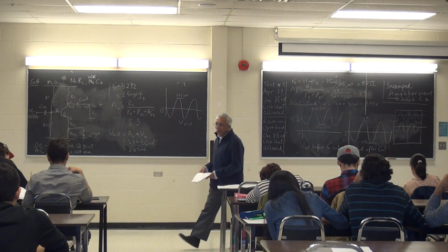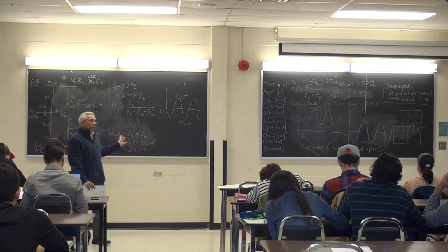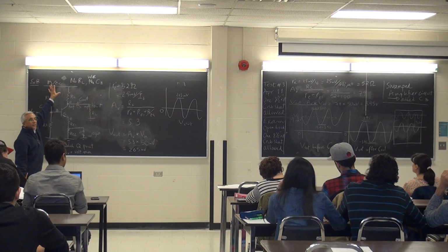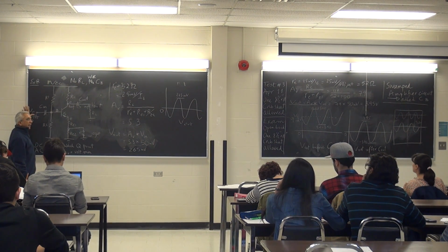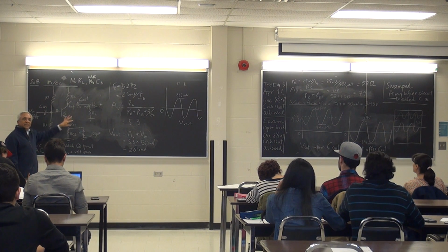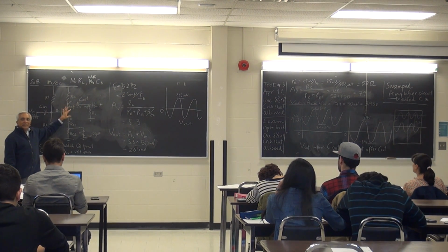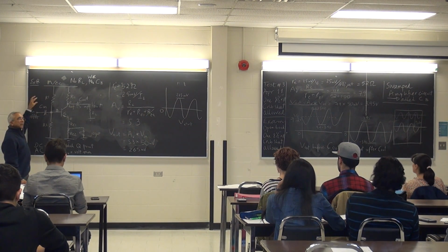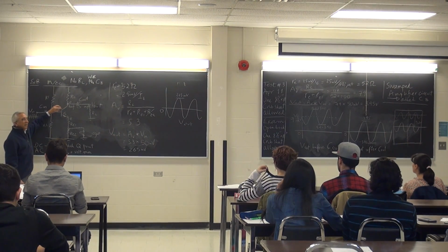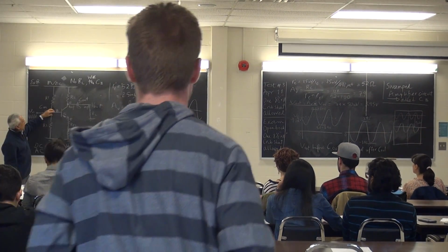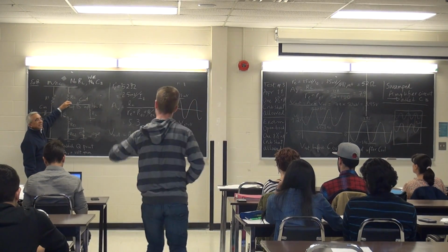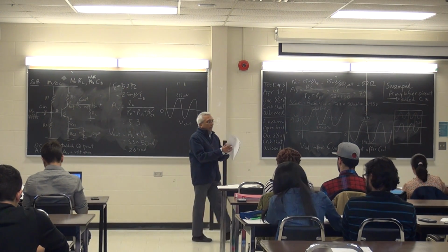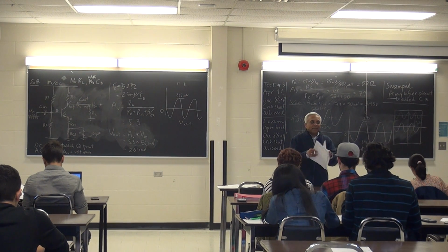The whole point of doing this is to tell you that in an amplifier circuit, we've got DC voltages and we've got an AC voltage coming in. And so there are two kinds of voltages at work here. There's DC plus AC, and basically this AC signal is shifting with the DC signal. At this point, it's going to be shifted by VB. At this point, it's going to be shifted by VC. Do you see that? Okay. So that's our notes for example 2. Let's go to example 3 now.